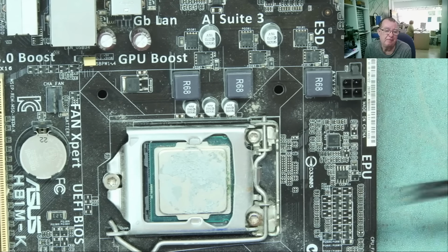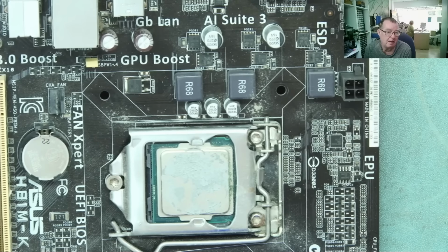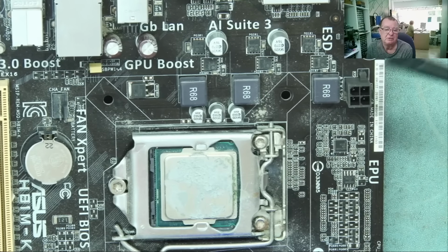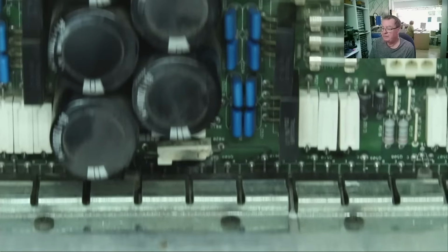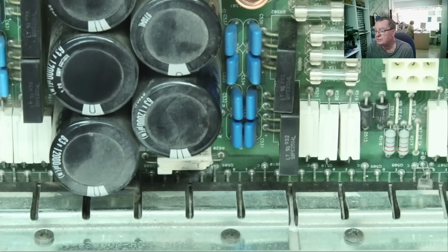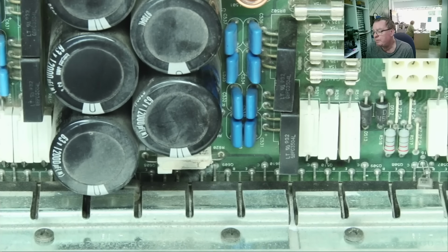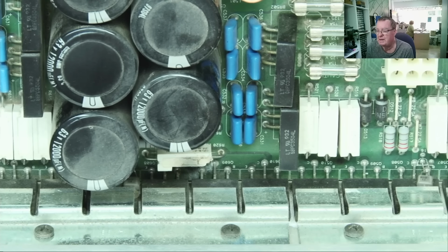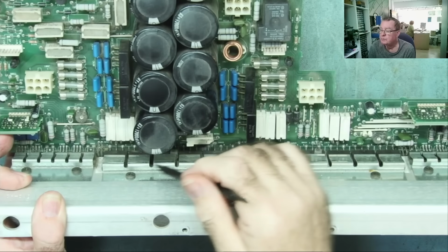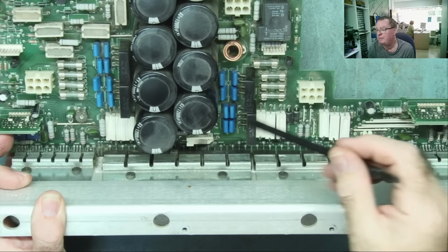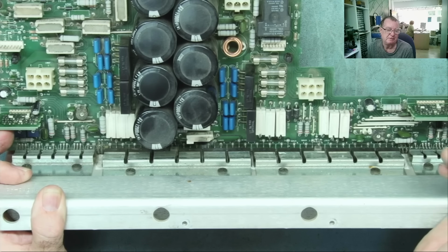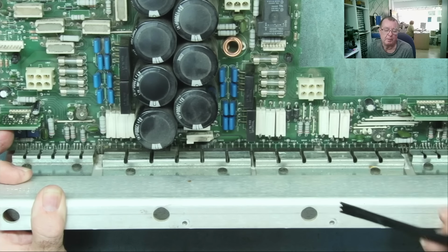Normally speaking, if the device is operating correctly and it was designed correctly, so the components are running well within their tolerance, these components shouldn't fail. They should last for the entire lifetime of the device. But they are common failures. Why? Well, often because of 2 reasons. One is abuse. In the case of this amplifier, this may have been overdriven. So effectively, some operators have been driving this amplifier above its rated specification. So that's one common reason for these to fail.